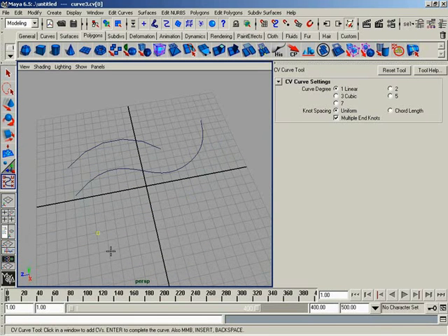Click. All right, we got our first CV down, which is an open box. We'll talk about the different shapes of CVs in just a few minutes. We'll click a second time, and now I get a U. Oh, I also get a curve. So that's one span because the curve degree specifies how many CVs are required, and then we simply add 1 to it. And we can look at that 1 as being an anchor point. That 1 is also always labeled as number 0, so it'd be CV0. So if this was CV0, this would be CV1.